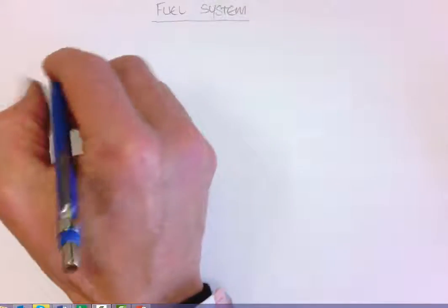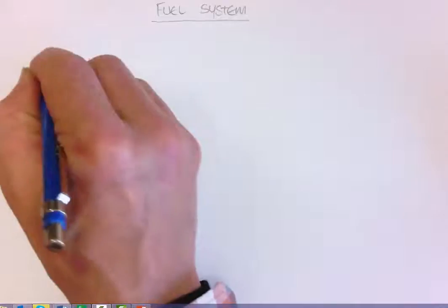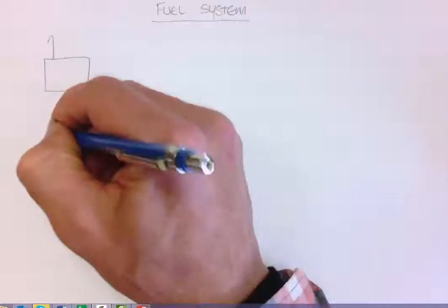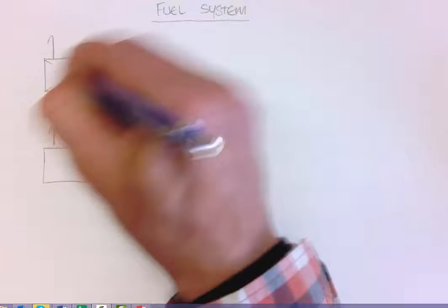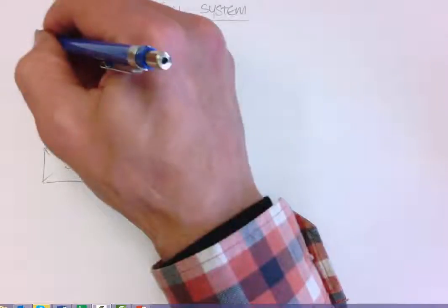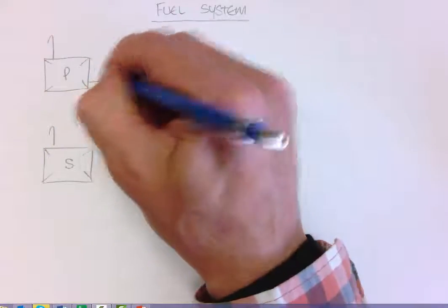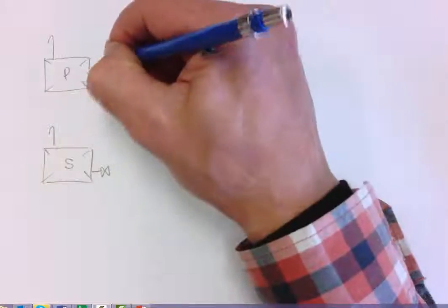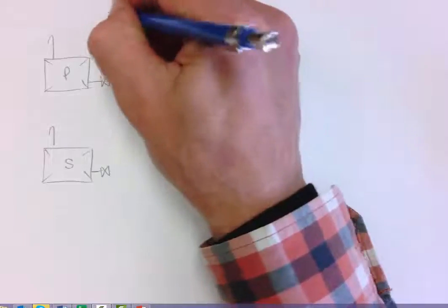So you need to be able to sketch up a fuel system. We're going to have a look at fuel in more detail with diesel engines, but if you're familiar with the system on your vessel, that's great. I'm just going to draw up a couple of systems that are fairly generic, which you may be able to use. So here I'm drawing a port and starboard fuel tank, and we've got a breather and our supply valve, which is a remote quick closing valve.